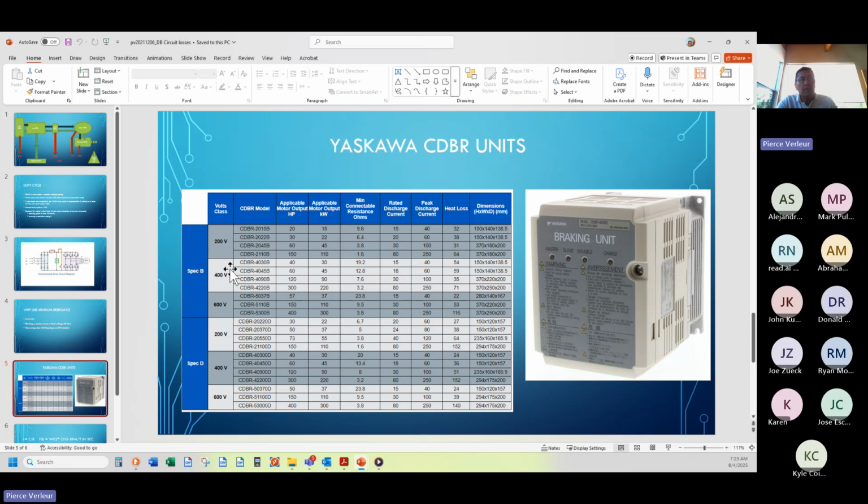Now, how do you house those resistors? Well, at least in a NEMA 12 in an industrial environment, you don't want dust falling on them, not because you need to protect the resistors, but you need to protect yourself from igniting stuff. Outside, NEMA 3R is good for resistors. Don't ever put resistors in a closed box like a NEMA 4. I mean, for obvious reasons.